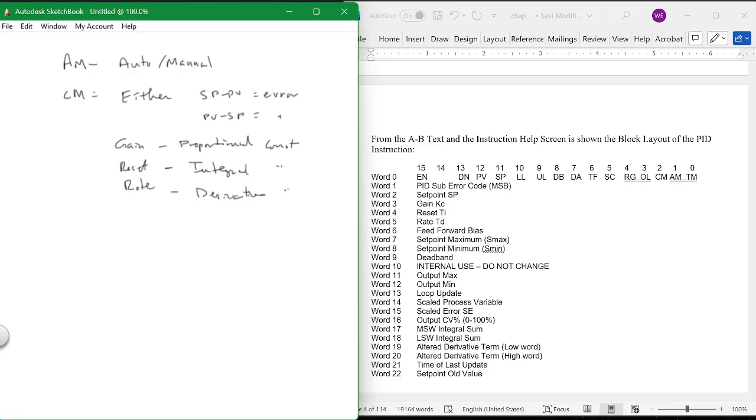Now, how do you find these? Did you look in a book? No. This is experience. Or you have a tuning algorithm, in which time you say auto-tune and push the button and it auto-tunes. So sometimes there's a program that finds these, and sometimes you have to find these yourself. There are folk that basically spend their whole lives doing nothing more than keeping track of these in their factory. And as the days change, as the season changes, and as the process changes, they change these numbers to optimize the way the process is running.